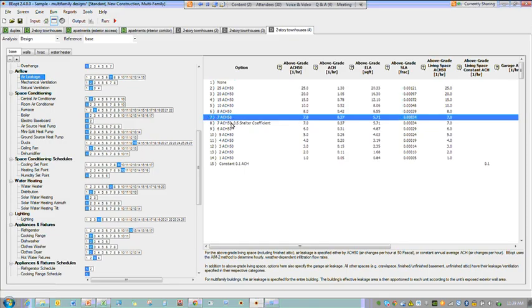And I should mention that this is the leakage to outside, so you would need to do a guarded blower door test to get this. And there's different ways of doing this. I think the ResNet guidelines for multifamily give some options for different ways to guard or blower door test for multifamily buildings. So you might do every unit a guarded test, or I think you're able to do a representative sample of units.